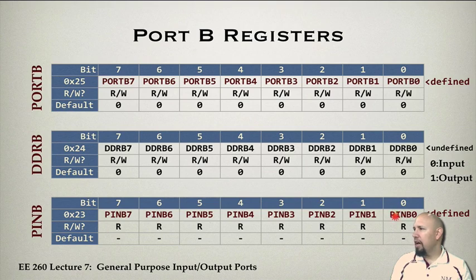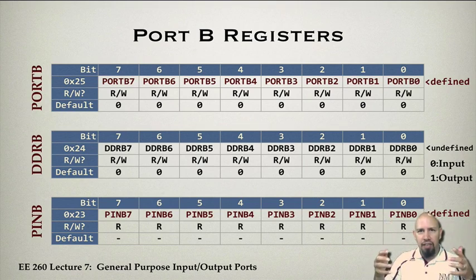So whenever you read from a pin, this is what you actually want to use. If you want to read what's happening on pin B0, for example, that's port B, pin 0. We showed you last time how ports B, C, and D line up with the Arduino pins, the digital pins and the analog pins. Remember that pin B2 relates to some Arduino pin. If I want to read a digital pin, I would find the associated port number and pin number to match, and we'll come back and do a little programming example after a while to show you how that works.